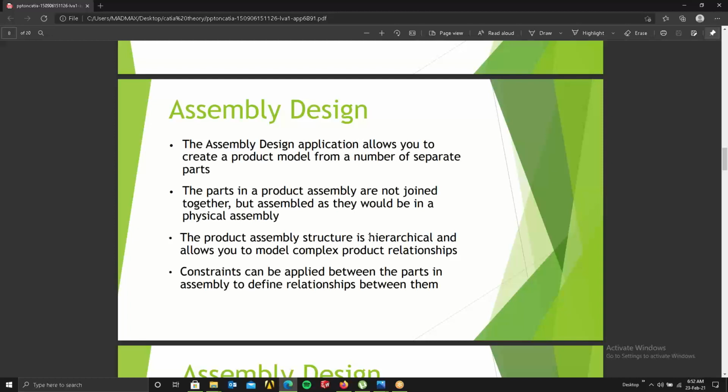The other company just goes with intuition, so their pen will have 0.8 mm or 0.5 mm thickness, and your pen will have only 0.3 mm thickness, which is adequate, and you'll add some ribs to make it strong enough.